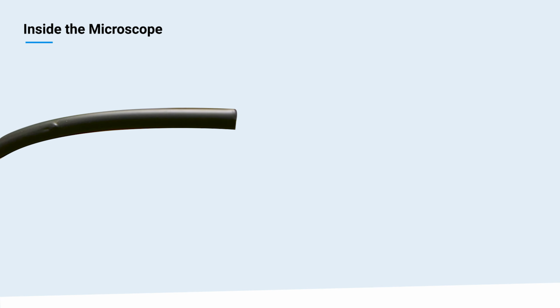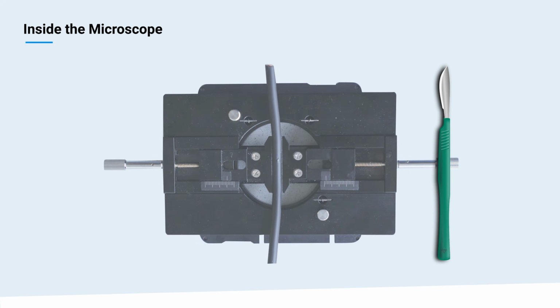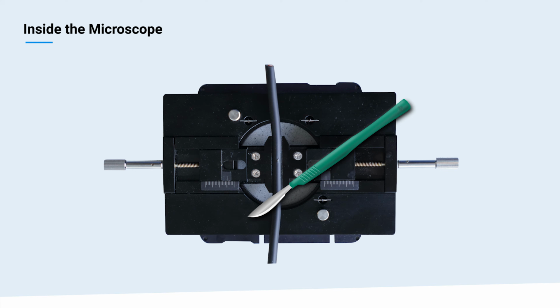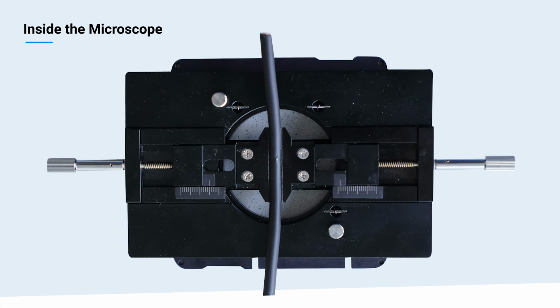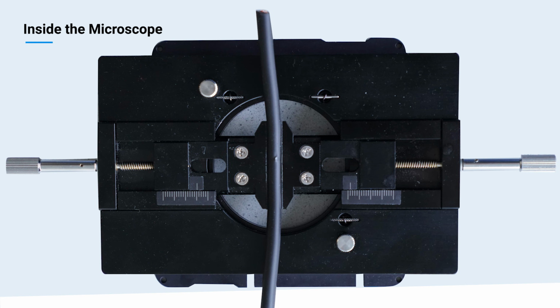So mirrors aside, how do we analyze the defect on this piece of wire? First, we'll need to do a little sample preparation. We usually don't need to do any sample prep for FTIR microscopy, but in this case we want to analyze underneath the plastic sleeve, so we'll hold the wire in place and cut the plastic away. Now we can see the defect, but this area is pretty small, about 2 millimeters long and 1.5 millimeters wide.